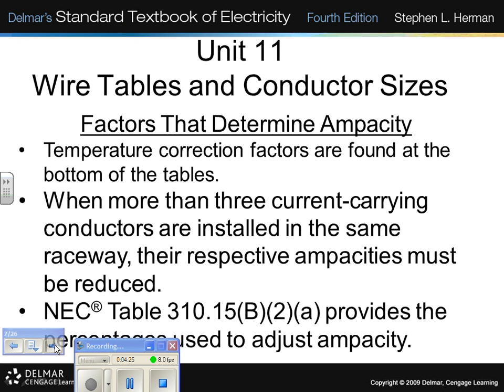And it's only 2 stages that I want you to remember. The first stage is for free. 1, 2, 3 for free. You don't have to derate wires up to 3 current carrying conductors in a conduit, right? So that's for free. 4, 5, 6 is 80%. Okay, that's a little hard to remember until you go to the next step and you go 7, 8, 9, 70%.